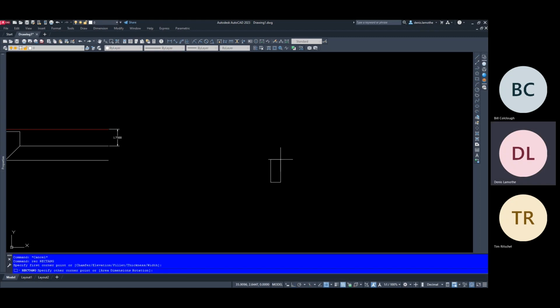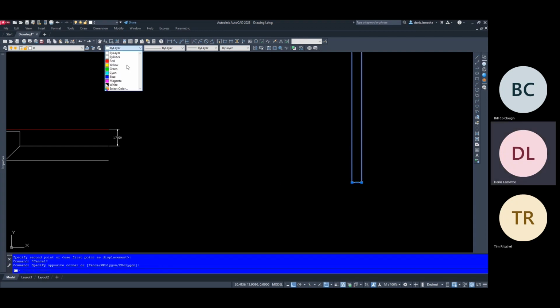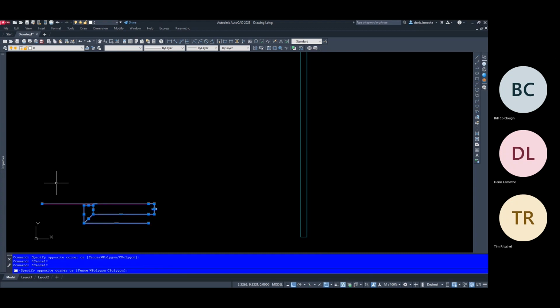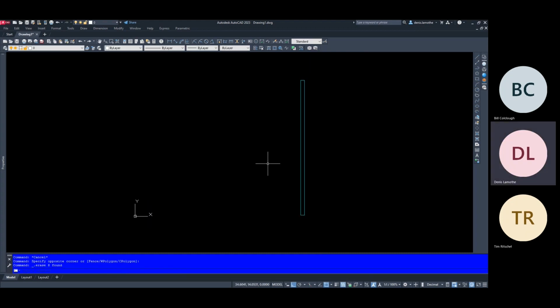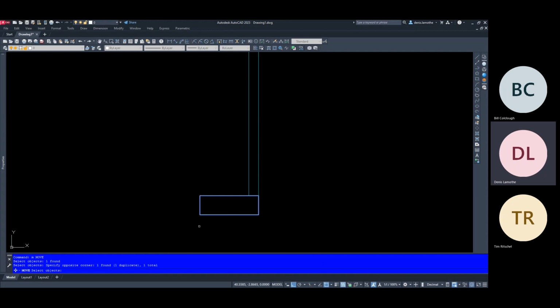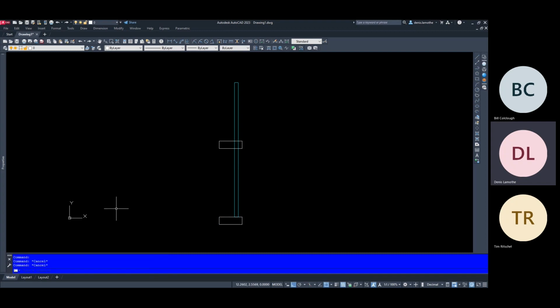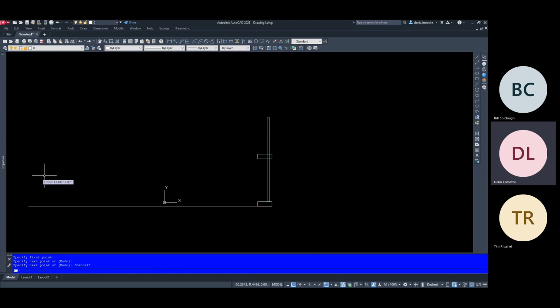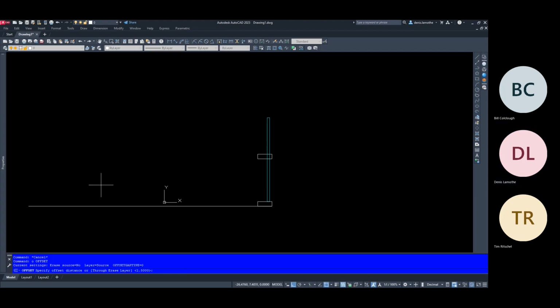Let's say we have a sealed unit 1 inch by, I don't know, let's just call it 30. And we'll make that a nice shade of blue. Say that's a curtain wall. We have a mullion that's maybe 6 by 2 inches. Those mullions will be maybe 1 inch that way. There might be an intermediate mullion somewhere. And we have our glass panel, say this is the floor, and I'm looking at this in elevation, 42.5 inches.